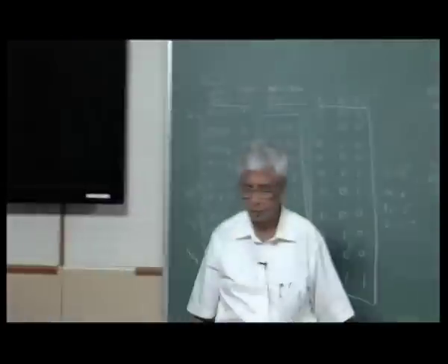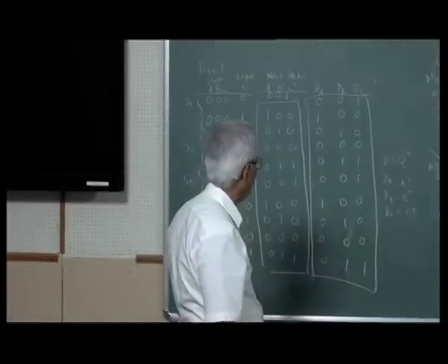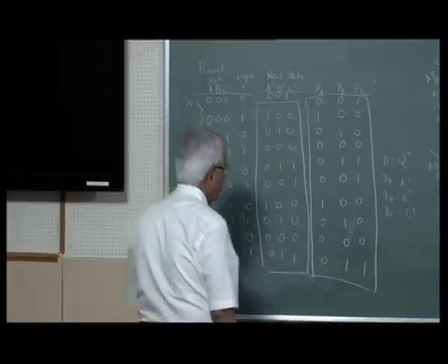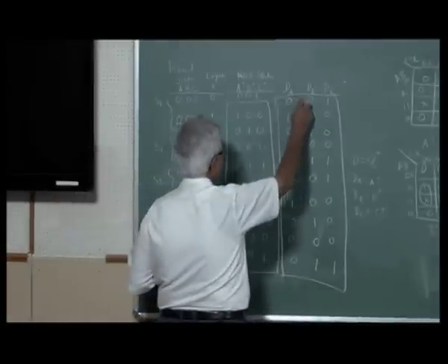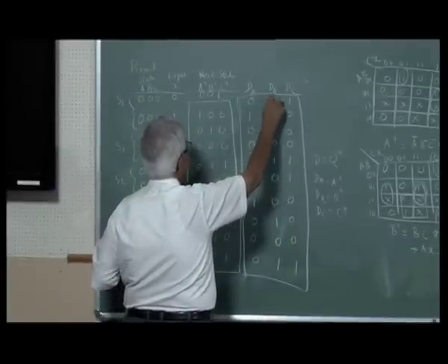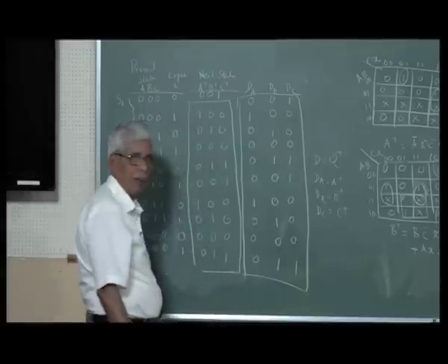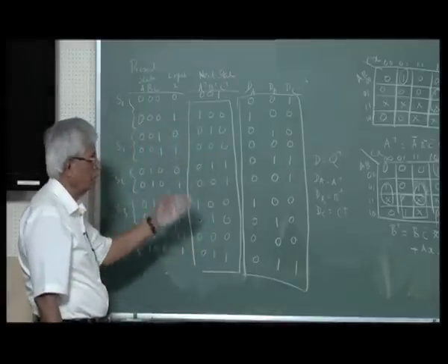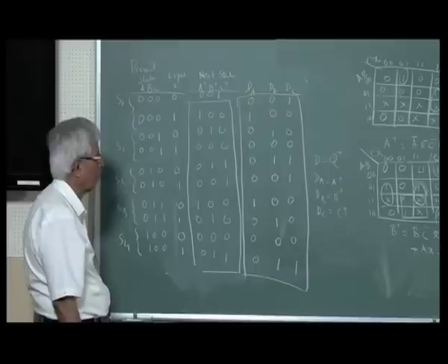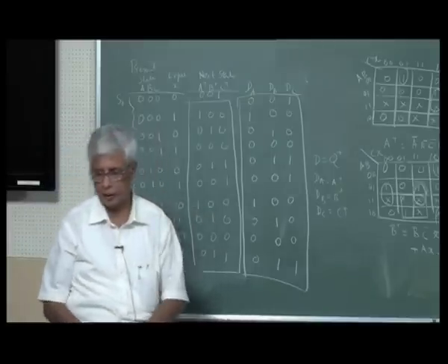That's it. Now, as I said, this is only D flip-flop. Instead if we are asked to do JK flip-flop, you have to write JA, KA, JB, KB, JC, KC. There will be 6 equations, 6 maps, simplify them, and you can draw the circuit. This is how you design a general sequential circuit.